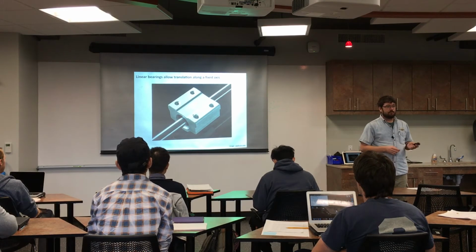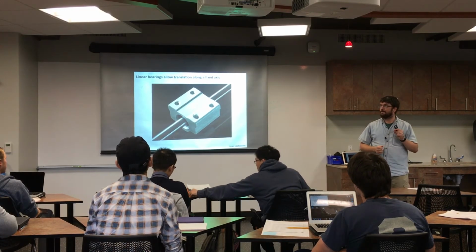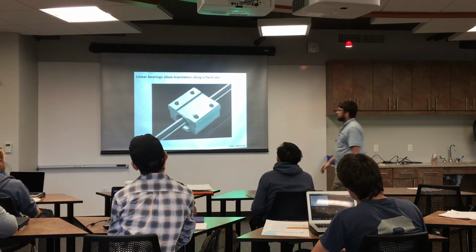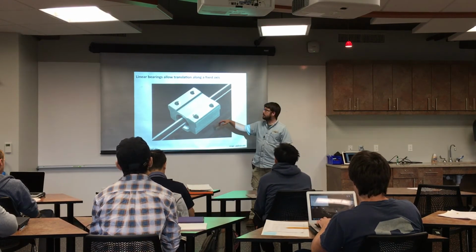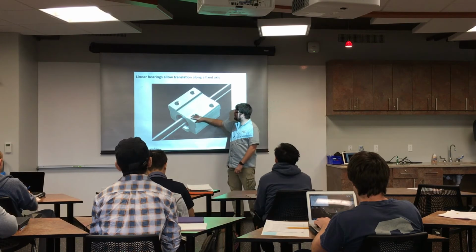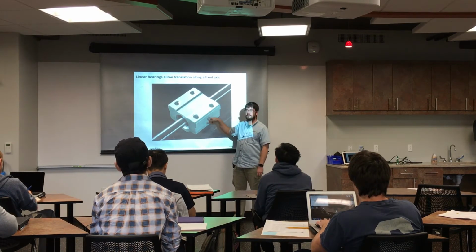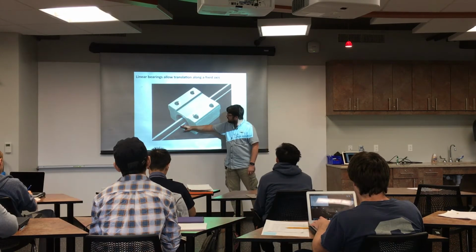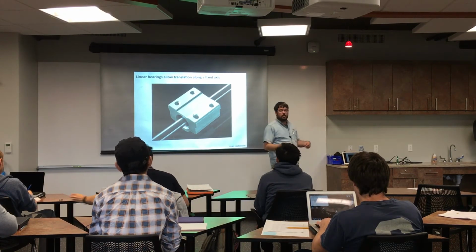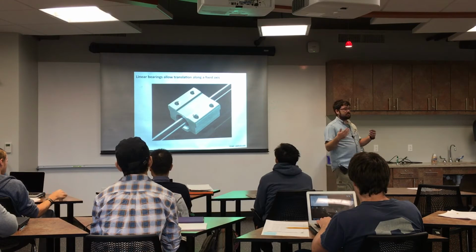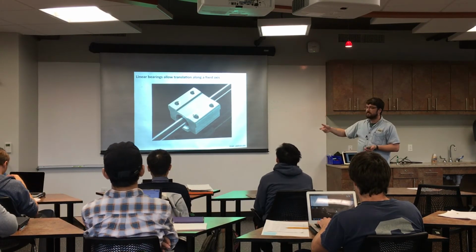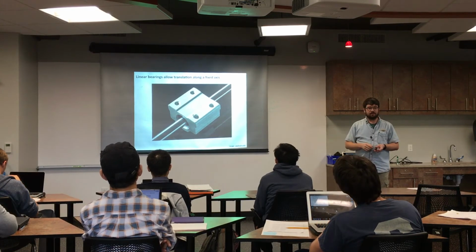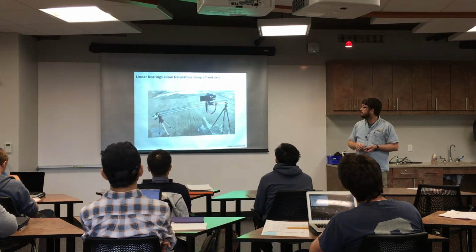Linear bearings are really useful for a lot of things. And they are bearings that work in one dimension, so you are constraining your system not quite just to 1 degree of freedom, because as this sits, it would also rotate around the shaft. You would have to fix it somehow. But the idea is you have a rod of a common diameter, 10 millimeters, 15 millimeters, those are kind of common linear bearings you can find. And this gives you a very smooth sliding surface to go along.